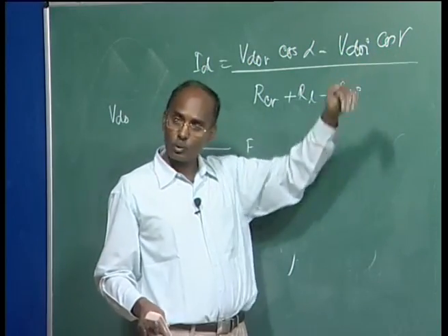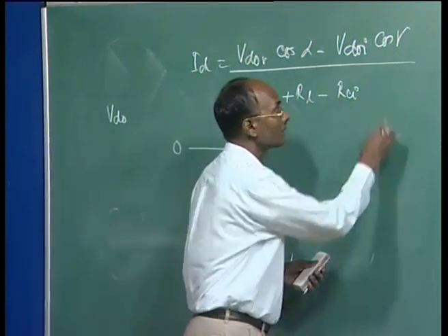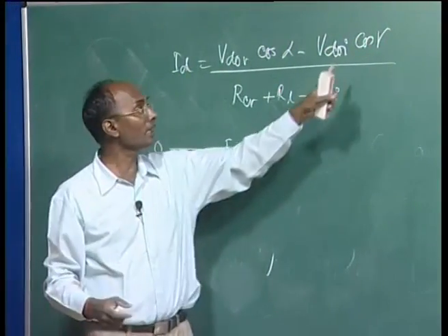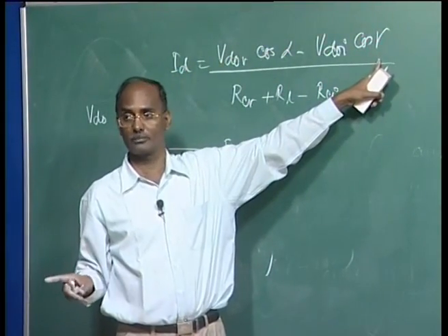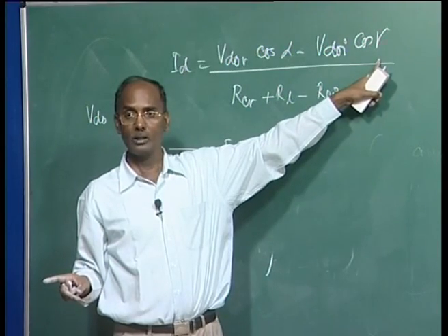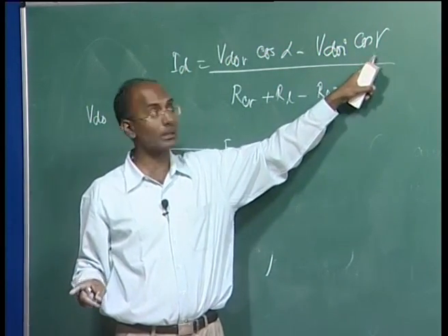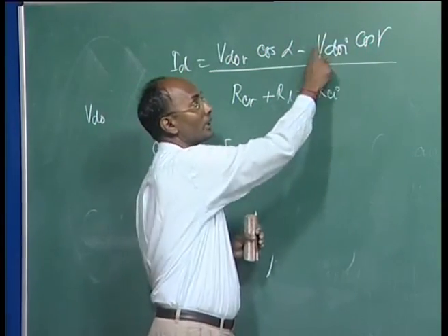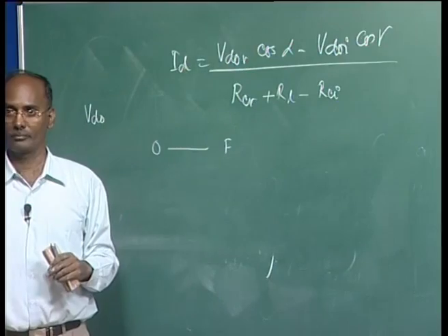We can increase this value, but again, if you increase this, your power factor is going to be worse at the inverter end. You can reduce this, but it has some limiting value and it should not go below it. And this then is your inverter end.